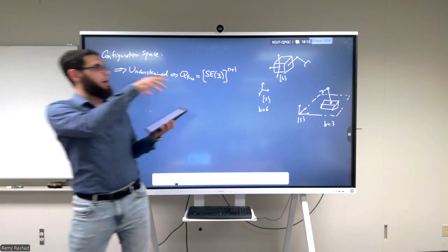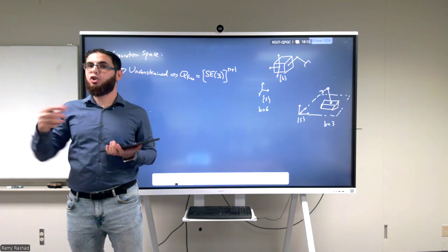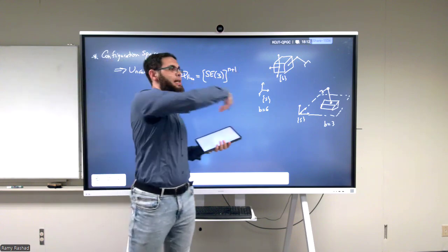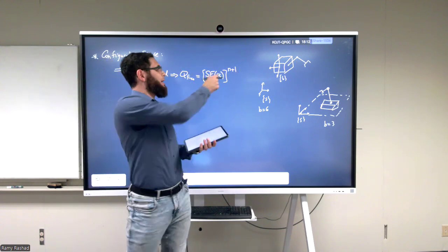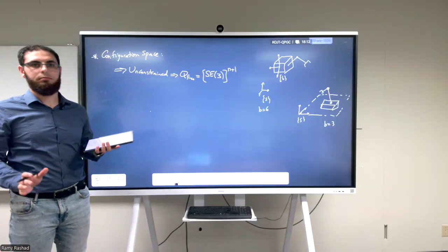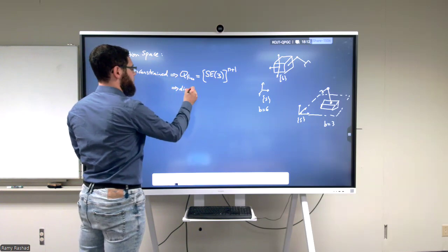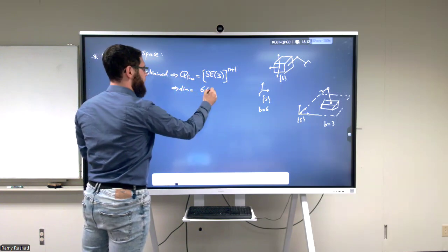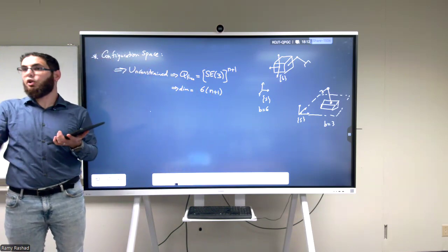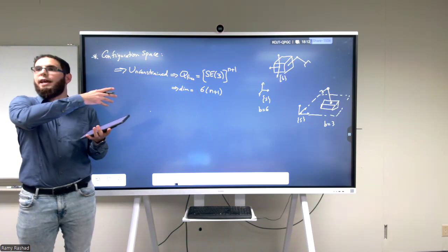Whenever we talk about a floating base manipulator, if you say I have an N link manipulator, you're assuming you have N links and an extra one, which is the base that's moving. So I have N plus 1, multiplied by 6. In the end, the dimension of this is 6(N+1). I have an extra 6 because I have a whole base that can do anything. But this is the unconstrained case.